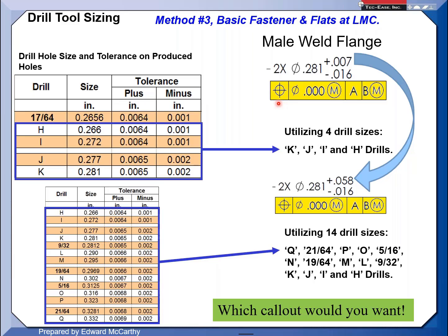So sometimes, if what you're concerned about isn't an axis control, then maybe you want position. In this case, what we're worried about was the hole's boundaries, so making this basic and using surface profile is applicable. You're protecting the boundaries. I didn't talk to that or add it. I didn't have it in my slides, but somebody did that. Kudos, that was pretty good. I like that. So there's more than one way.